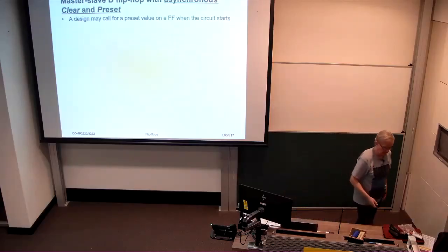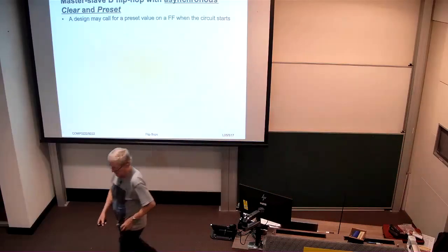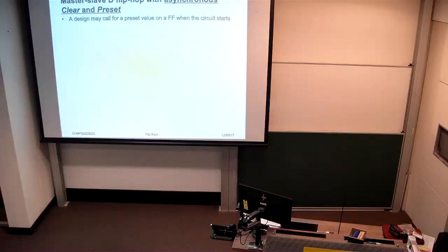Right, let me resume. All right, so often in a system, when you start the system up, you want particular values established on the flip-flops prior to the circuit actually being active. That means we want to either preset or clear the value of flip-flops. I mean, the normal thing to do would be clear all of them so that you know that what you've latched is the value that was actually present, not something that was pre-existing in the flip-flop.